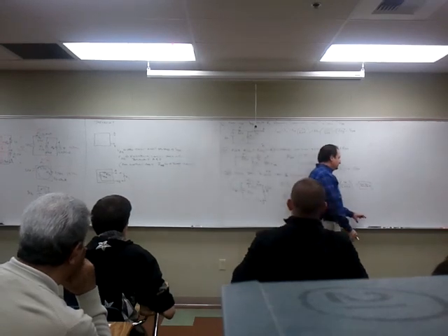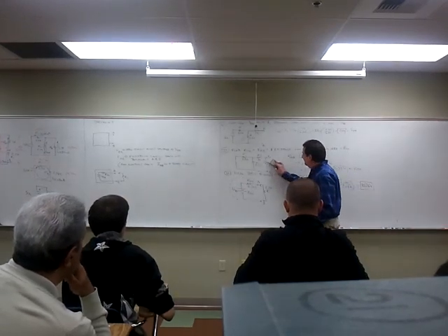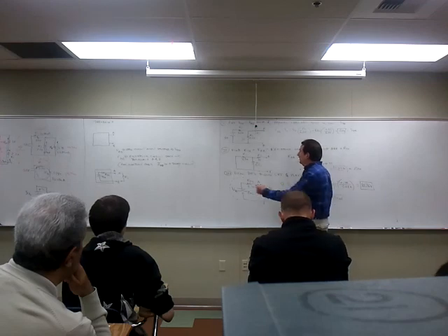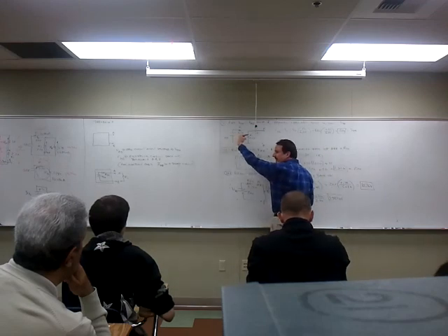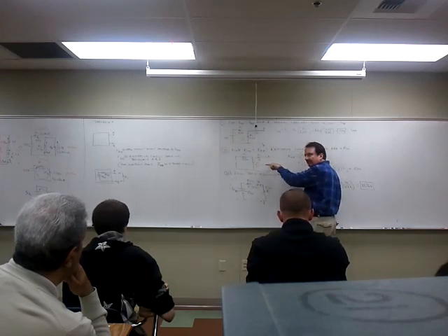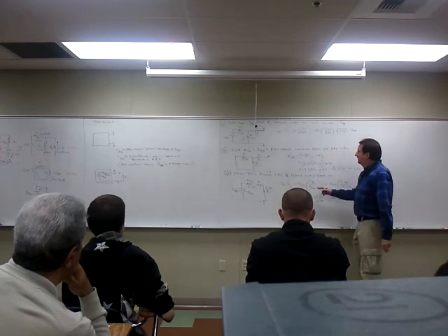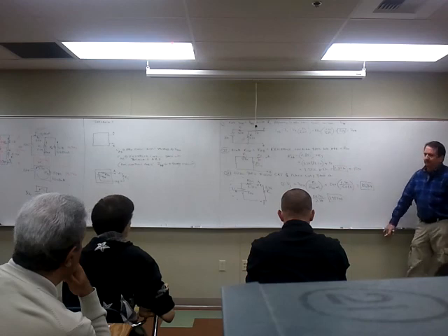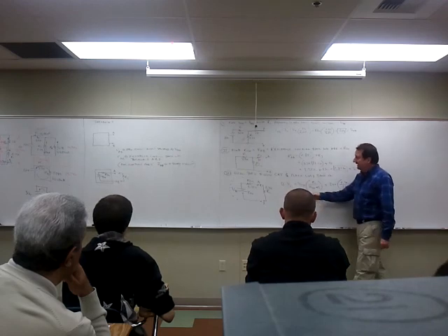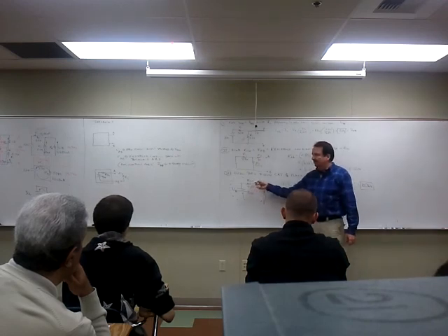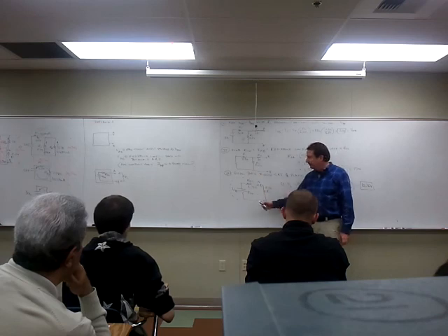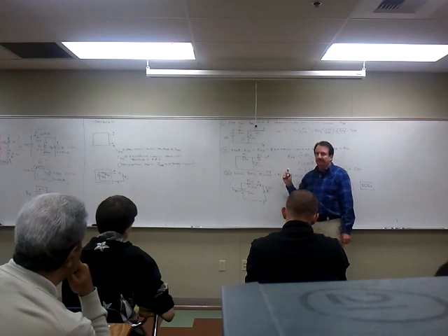So when you say resistance looking back in, it means a different perspective. R total up here is looking that way. R total here looking this way is R Thevenin. So looking back in, you got 2.32K. Where does it go? Down here. That value becomes this R Thevenin. So what did you find? V Thevenin is step 1. R Thevenin is step 2.